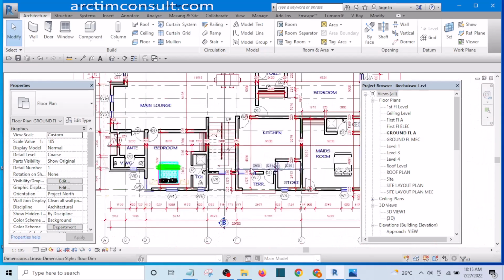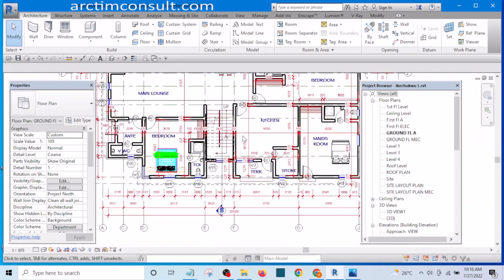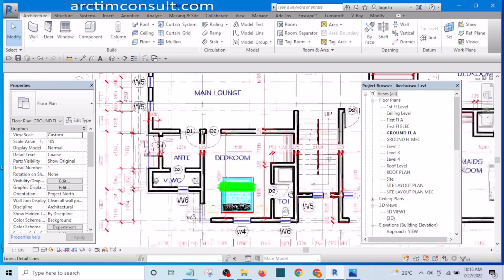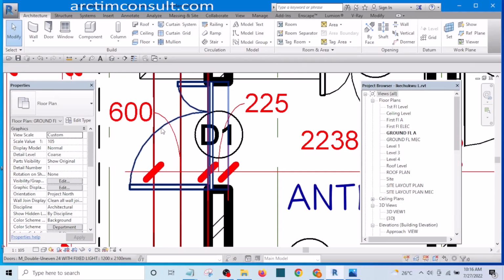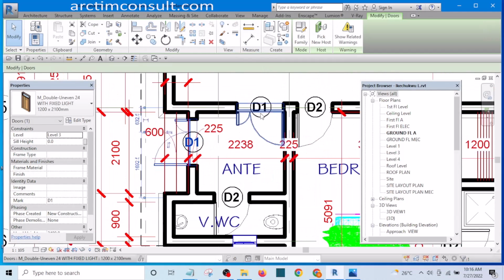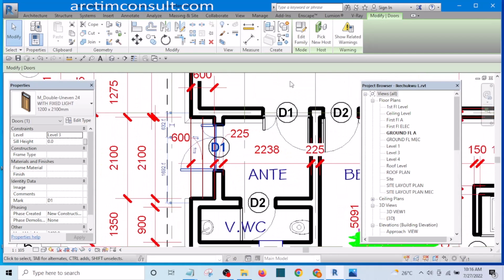Okay. So we are going to update that so that we can have a longer worktop somewhere here. The door can even be here, it's better. Okay, now let's copy the door we want to use. This is the door we want to use. This is it here. You can see it. It's one of the doors that I created some time ago in the past. So I want to use that.